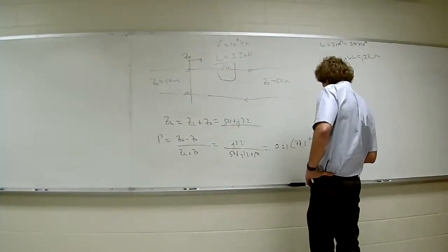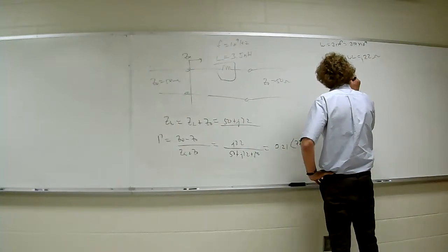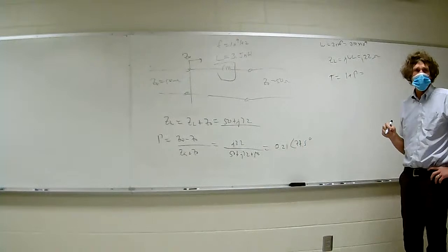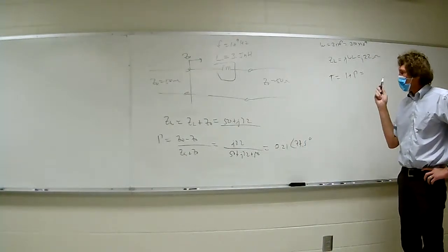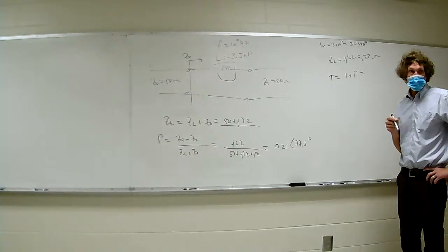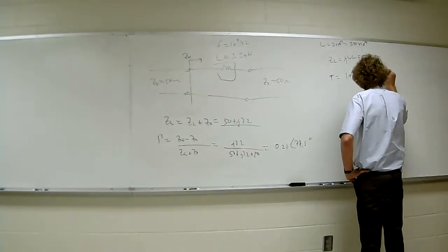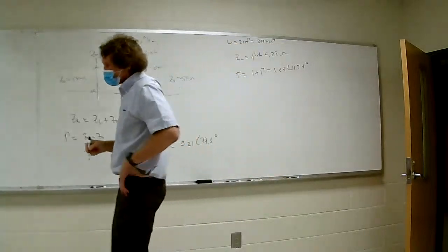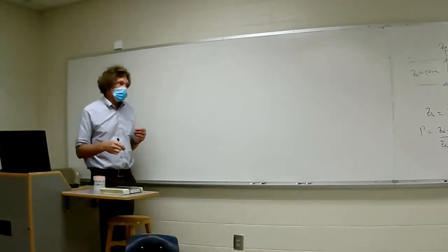So that's the reflection coefficient. And what's the transmission coefficient going to be? 1 plus the reflection coefficient. It's just a hair over 112 degrees, I think. Can somebody just take that reflection coefficient, add it to 1, and give me the magnitude and angle? 1.07 at an angle of 11.34. Yeah, that's right. So with that, we got the input impedance, we get the reflection coefficient, we have the transmission